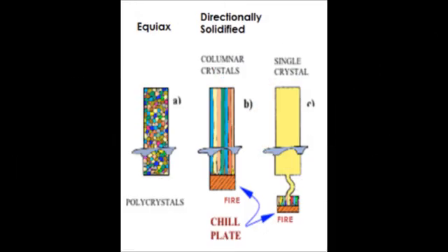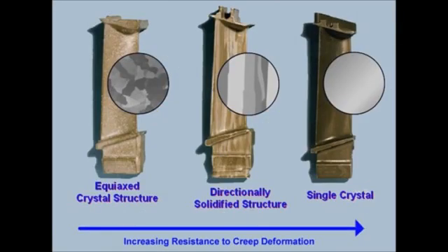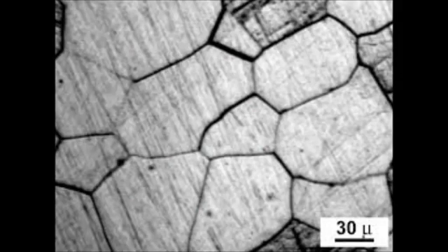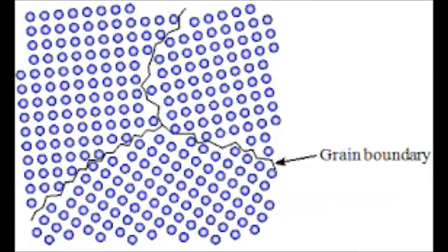However, the innovations didn't stop there. There have been 3 different ways to manufacture an engine turbine blade with the HIP: equiaxed casting, directional solidification, or DS, and single crystal, or SC. Equiaxed castings are crystals that have axes of approximately the same length without any order. This type of casting creates grain boundaries or defects in the material and can form failure points.